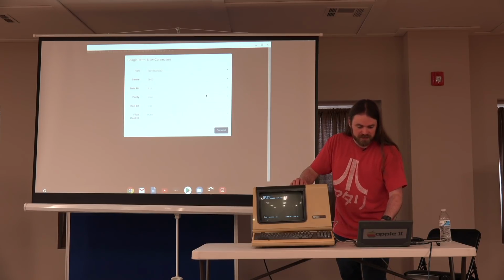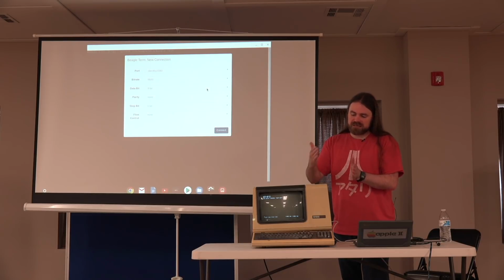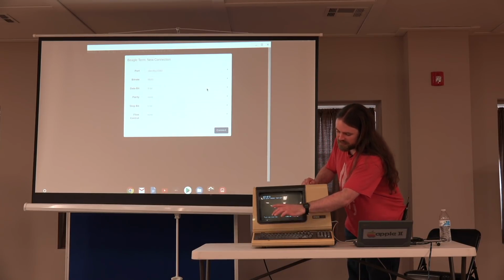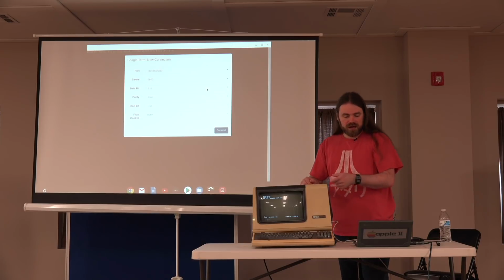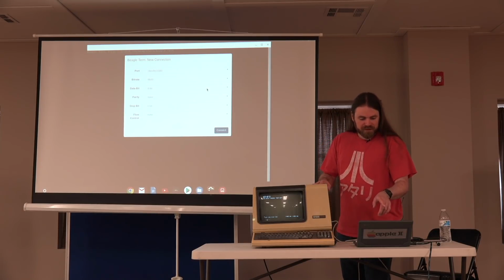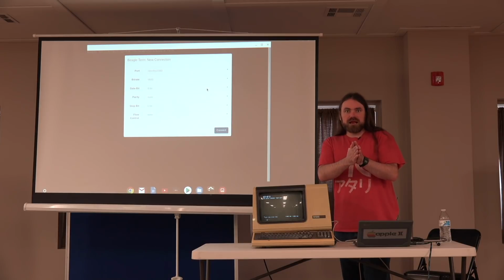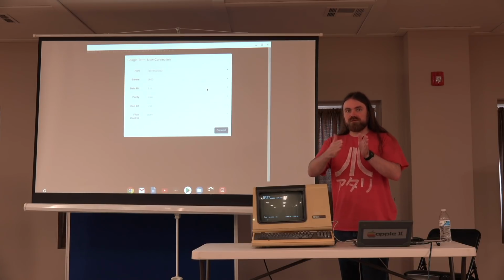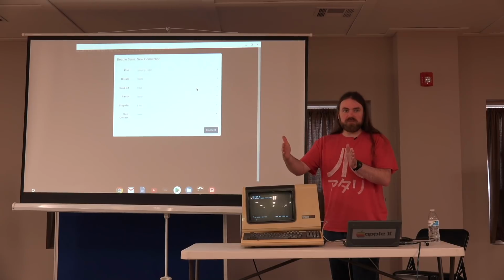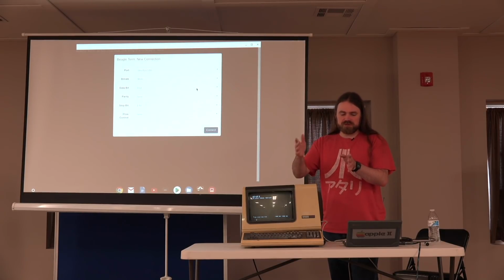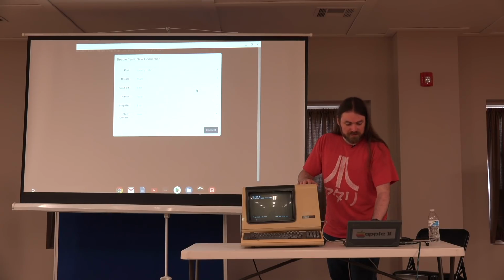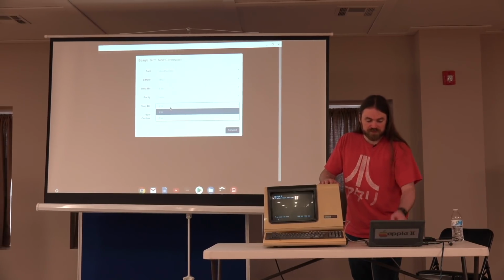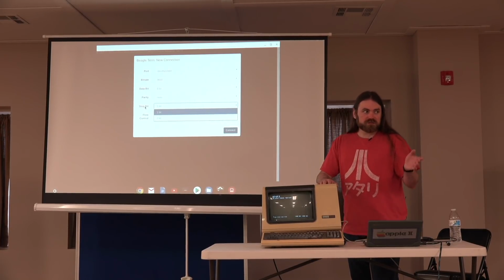You've got the ASCII characters being sent by the terminal. If I hit A, it sends the ASCII character for A through the serial port to the computer. Is that ASCII character represented by just the 7 bits or the full 8 bits? Then there's the parity bit, an error correction bit at the end, whether you have it or not. No parity is pretty common, but some of the DEC stuff used even parity. Some other things used odd parity. Then a stop bit. You can have either 1 bit or 2 bits. 1 bit is common.